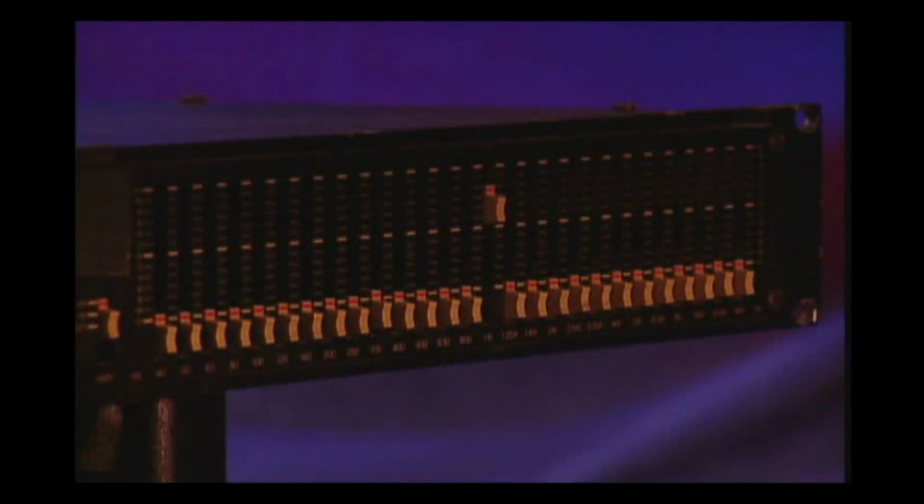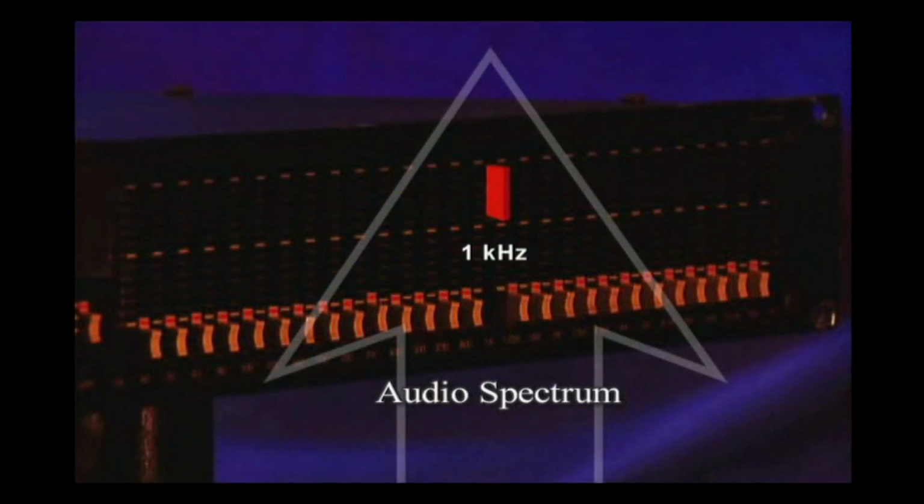Basically, this is done with a circuit inside the EQ which acts as a filter. The EQ circuit is designed to filter out the frequencies other than those it's meant to affect. It's this aspect of the design of equalizers which makes them useful. You can control and make changes to just a particular frequency or a group of frequencies within the audio spectrum.